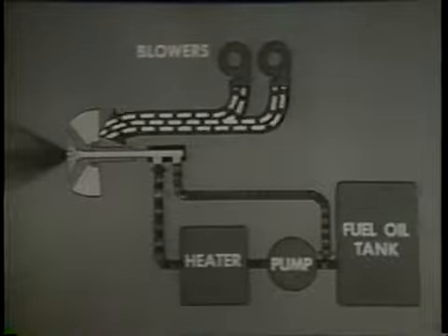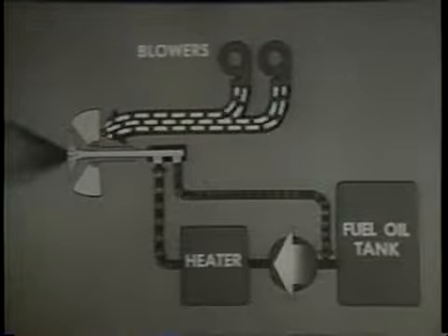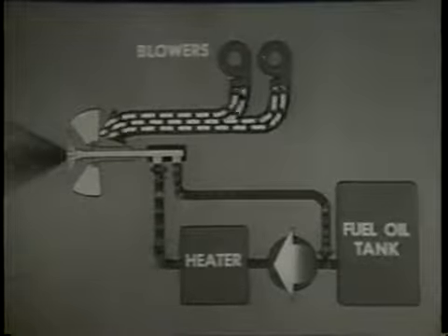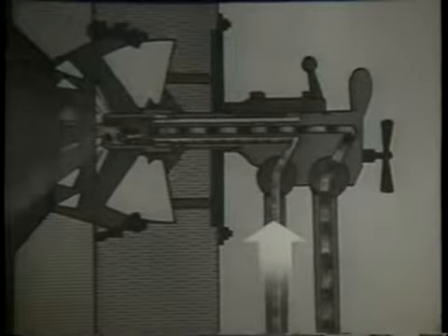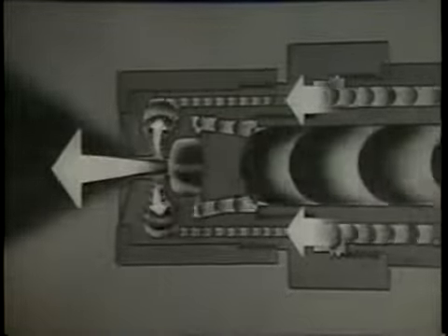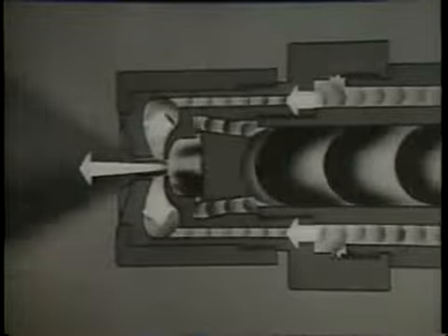In controlling the fuel supply to the burner, you keep the pressure on the oil entering the burner constant and at the maximum for the system. You vary the pressure on the return line. When you close down on the return line valve, less oil can get through. As a result, the pressure builds up in the return line. This greater pressure forces more oil into the furnace than before. When you open up on the valve, it passes more oil and return line pressure drops. Less oil enters the furnace.